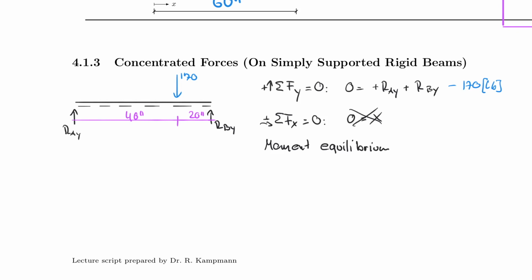So far, the only thing we have done with moments is we calculated moments, like we called it acting moments. But now we want to use the moment to actually find the answer for our support reactions. So I asked the students in the classroom to apply moment equilibrium to the system without any further guidance. And so what we usually end up with then is an equation that says, hey, why don't we just take the sum of the moments about, let's call this here point C, about point C. And of course, we'll take counterclockwise positive, and we say that's equal to 0.